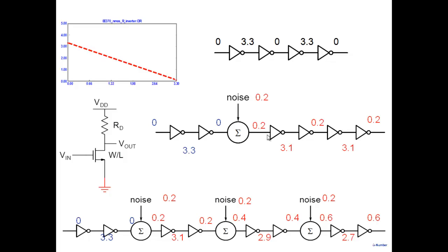If you inject 0.2 volt noise here, then maybe 0.1 volt noise is present here. And then the next one, even half, so at least it attenuates it. So what are you looking for? You're looking for a characteristic not with a gain of 1, but what kind of gain should be there? If it has to reject it, what should the gain be? Reject it. So you introduce a perturbation here, and we are saying this inverter should reject it. No perturbation at the output. What does that mean in terms of gain? 0? That there should be a place here where the gain should be 0.